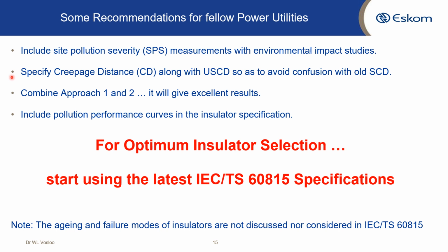It's the same. So that is an excellent way to avoid confusion. I've had the situation where guys were totally under insulating a substation in a very heavy environment because they got the two values confused, and that square root of 3 caused quite a costly change that had to take place in that situation.